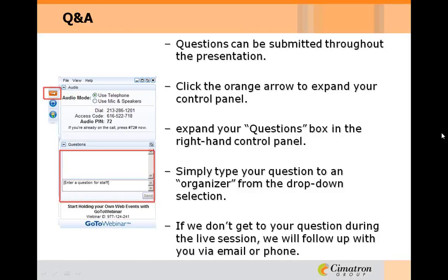Yeah, absolutely. We showed a little bit of mirror, and you saw that when I mirrored the surface, it was a copy. Mirror is something that we're working on right now because it's at a basic level of functionality. What mirror will do is always copy. It doesn't move. So if you've got an existing tool design and you want an entire mirror of it, it's going to take you a little bit because it will certainly pick the parts, mirror them over, and you'll have that copy. If it's 2 parts in one mold, then it's really not any different than what I was showing. Instead of the 1 part twice, you'd add the left on one side and the right on the other and work on them in that fashion.